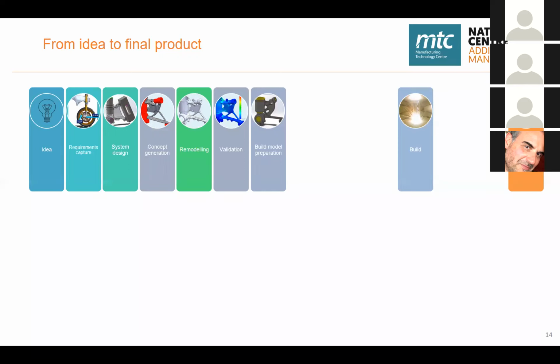So we add that material and prepare the part for the building. And then after that, what we do is what is called build preparation, which is a step where we add supports or orient our part according to buildability, and as well stack more than one component. So what we get out of this step is the file ready to go to the machine.